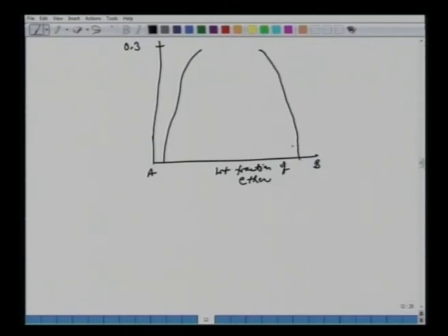Now the feed first stage 0.3, it's a pure solvent. So this is 1 here, we connect, so we are mixing it in the first stage, and we mix and then we settle. So knowing the amount of this 0.3 amount of the solvent, we can write A. So let's say for the feed added, solvent added here, it gives us R1 and E1, raffinate and extract phase, they are in equilibrium.